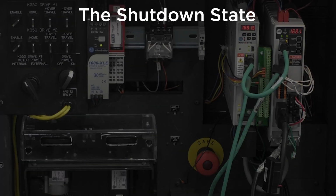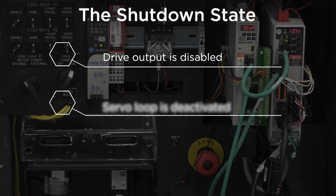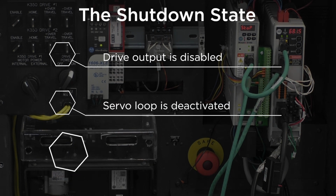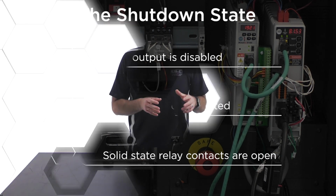The MASD and MASR instructions are specialized instructions associated with a specific operation mode of an integrated axis of motion called the shutdown state. The shutdown state of an axis is the condition where the drive output is disabled, the servo loop is deactivated, and any available or associated solid-state relay contacts are open.